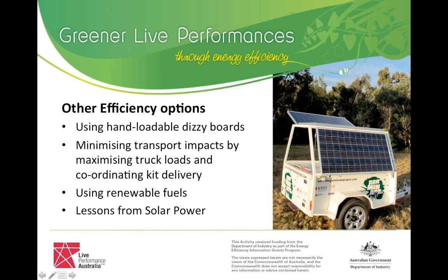and also you've got to manage the size of the battery bank that you've got. I know some people for daytime events, when they're running solar, tend to rely on having a lot of solar panels themselves and fewer batteries. My preference is to have a heavier load of batteries, and certainly plenty of panels, but to make sure that you've got a really significant store of batteries. Otherwise, if it becomes cloudy, or it moves into the evening and the load is greater than you're expecting, you could find yourself particularly stuck.